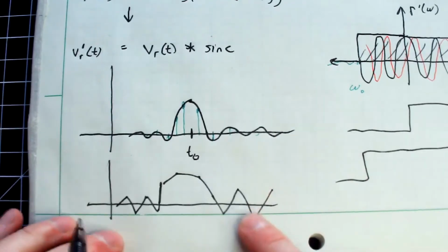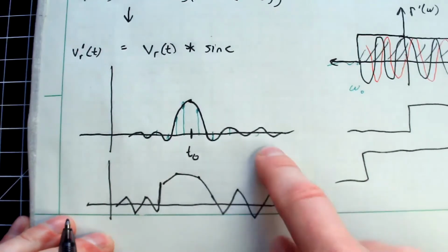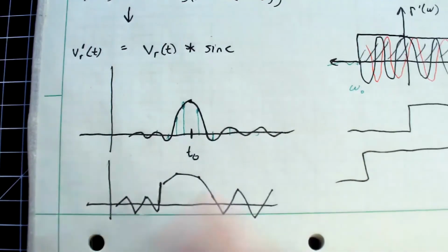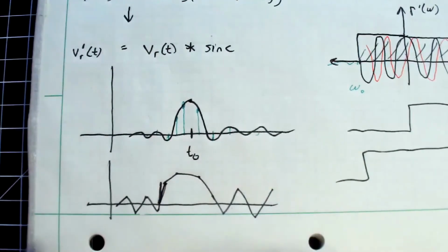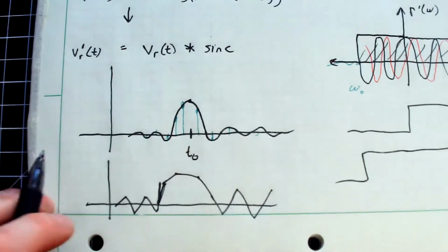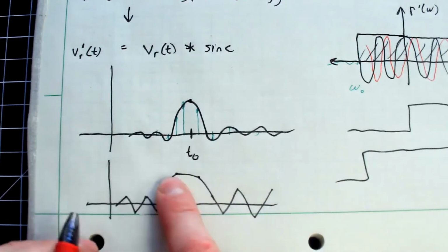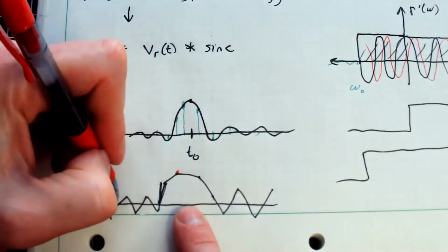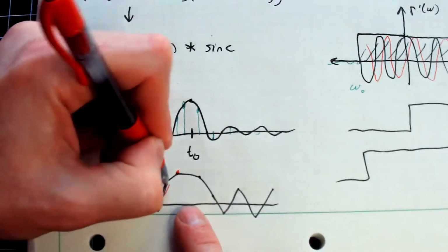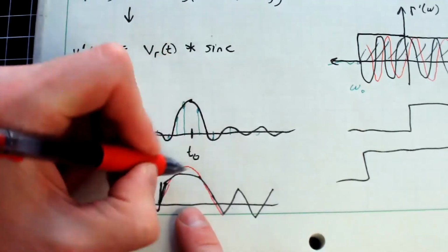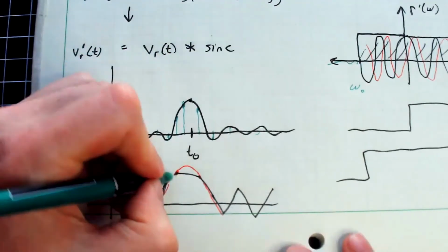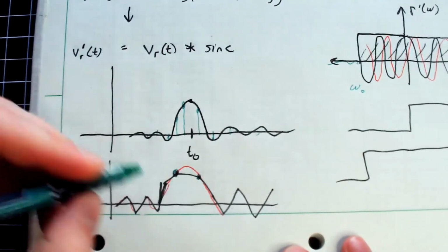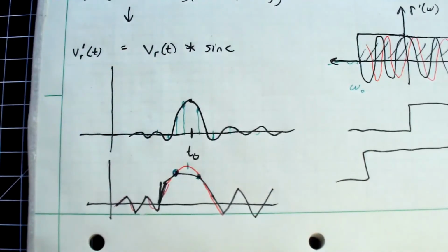When you go through all that signal processing, you get this discretely sampled version of something that wants to look like a sinc pulse, but it is downsampled. I'm sorry, I didn't quite draw that very well. And depending on how coarse your sampling is, it looks pretty nasty. So what happens is this creates a problem where it looks like my peak might actually be here in my sample data, when in reality, it might be up over here a bit. So you have this problem of here is where I think my true peak is, or maybe it's there, but the actual true peak is here.